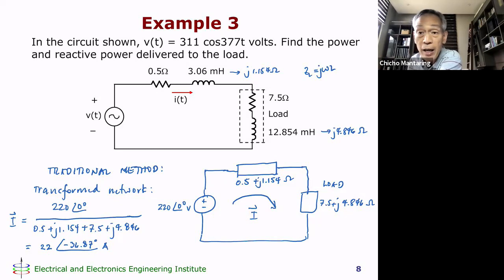If that transmission line is short, then this can be neglected. But if it is long, then you have to take into consideration its impedance. And the transmission line is almost always inductive, so it will consist of a resistance in series with an inductance.